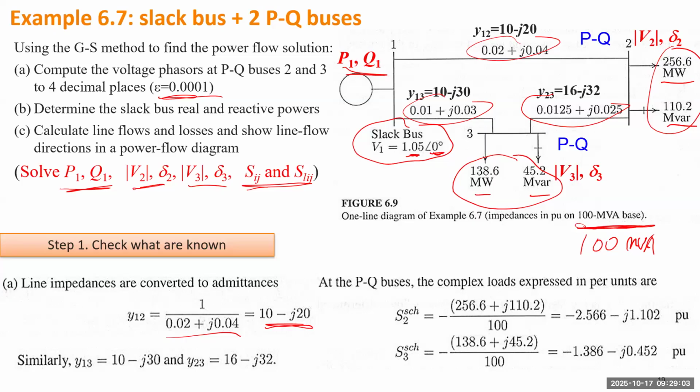Because when we call the complex power injection to each bus, we assume the direction is from the external into the network. So for PQ buses, if they actually represent loads, their P and Q will be negative. Here I indicated the direction as power leaving the network, but when you construct the complex power for each bus, you need to add a negative sign.